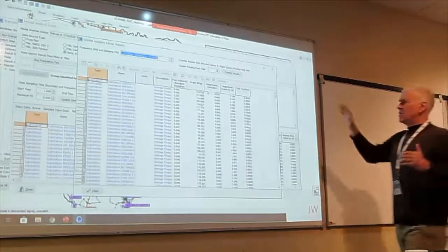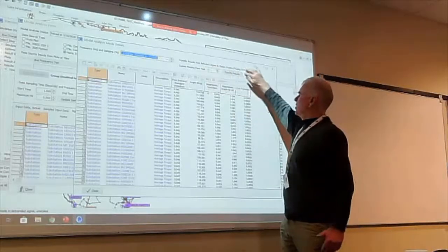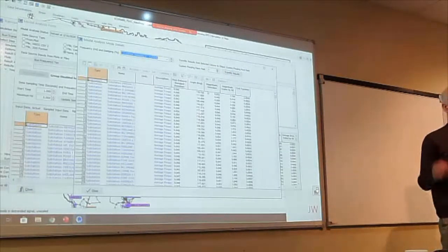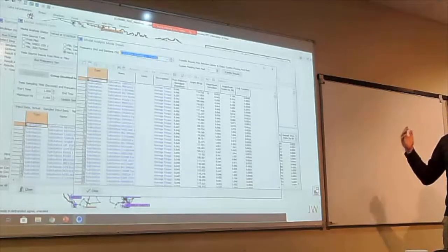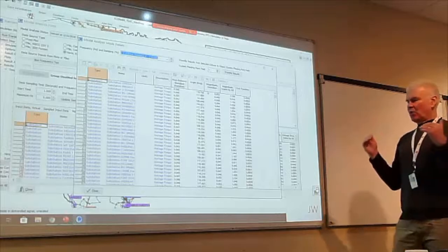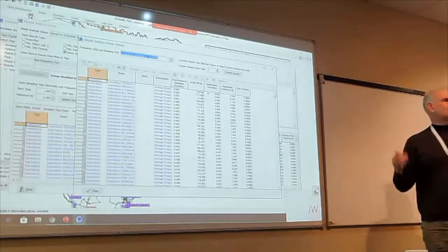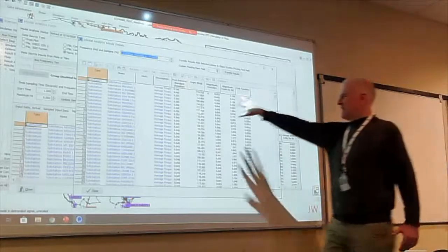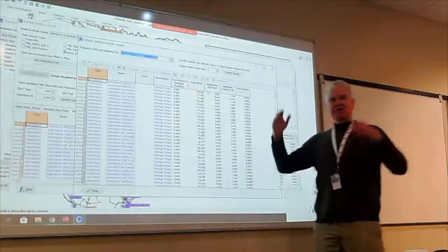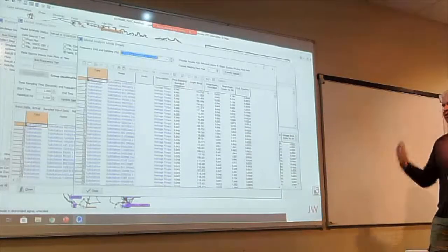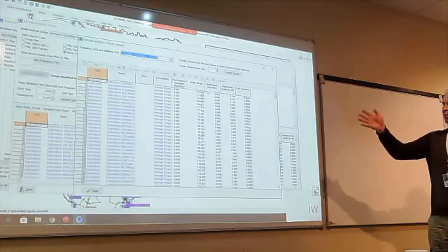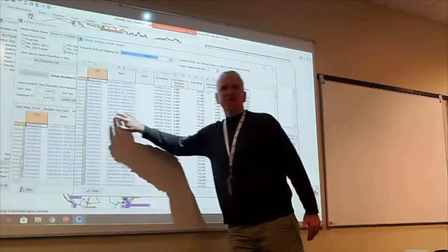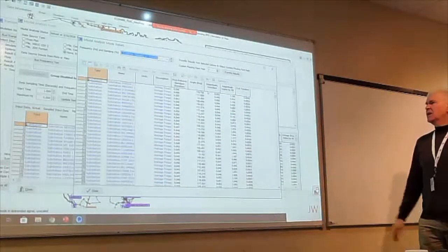So what we did is we added this up here that says transfer results from selected column to object custom floating point field. This feels a little kludgy and maybe we could automate it, but PowerWorld for all the records has custom floating fields that you can use to display stuff. This data is not yet associated with the substation. This is just modal analysis, which took in a bunch of signals. In PowerWorld, though, because the source of those signals was transient stability, we have maintained a link to the substation record. So we can transfer data there.